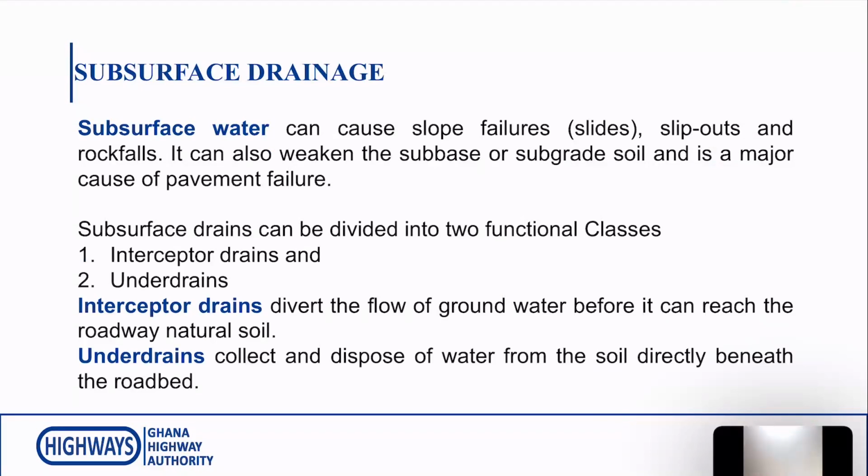You remember a couple of years ago, we had the rocks near the Pedrazi falling off. This was caused because of subsurface water running through the rocks and weakening the rocks and making the rocks fall. So it's very, very important to look at subsurface drainage. And it's a major cause of pavement failure.